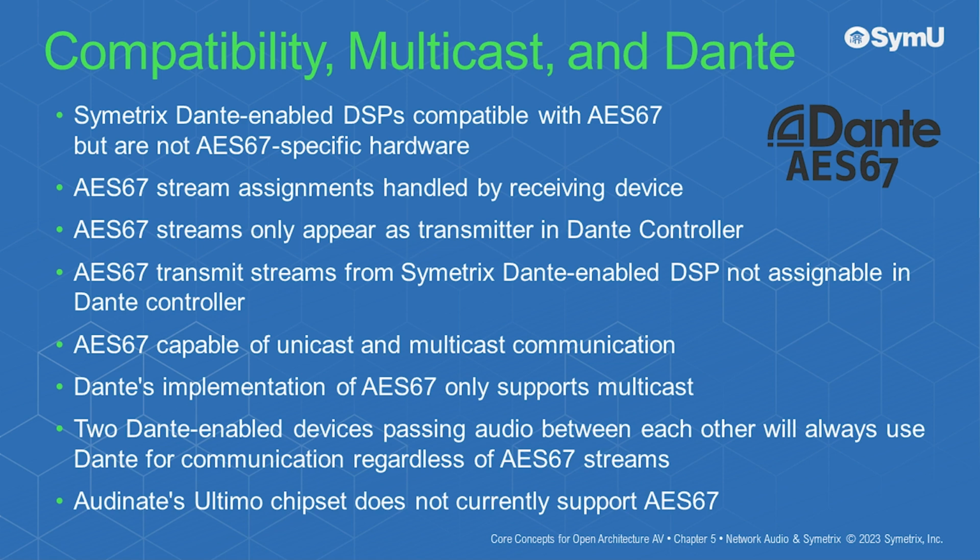AES67 stream assignments are handled by the receiving device, and streams will only appear as a transmitter in Dante Controller. AES67 transmit streams from a Symetrix Dante-enabled DSP will not be assignable in Dante Controller.